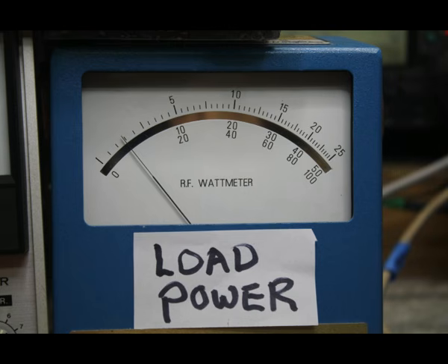And we also find that into the load, now we only have about 3 watts of power delivered out of that 10 watts that we have at the transmitter end. So we've lost a lot of power. Now some of this is because these meters are not exactly tracking at such a low power level. I'm a long ways off full scale, so these meters are starting to be a little bit inaccurate down on the low end of the scale. You usually don't want to use a watt meter at that point, but we're doing it just because this isn't all that important anyway.